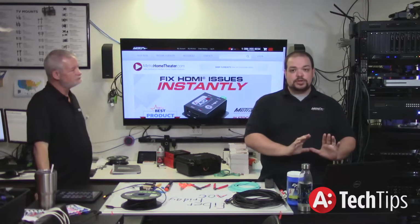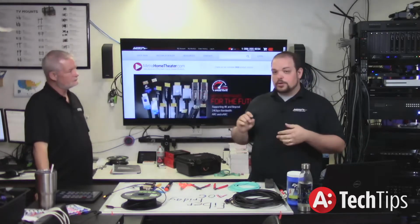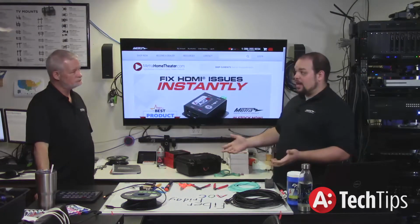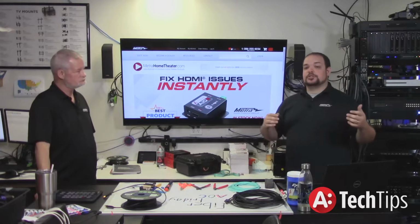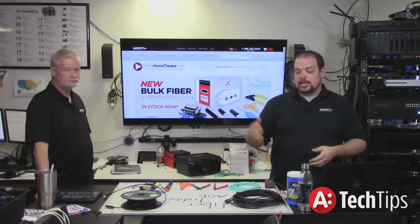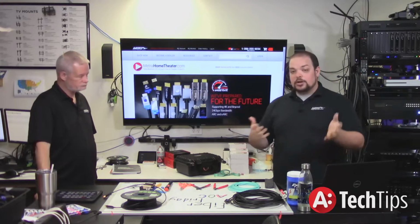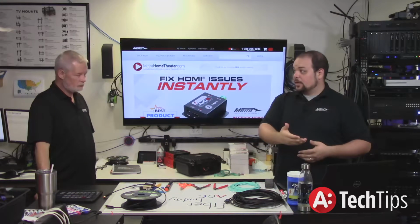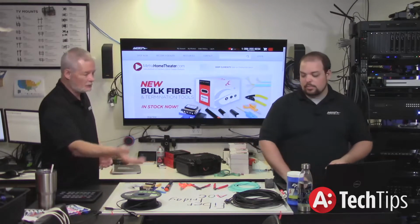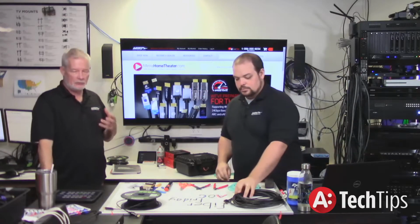If you're going to be using it solely for an HDMI connection, put in an HDMI AOC cable. If you're doing a pre-wire and you have an opportunity to put the bulk fiber in, and in the future you're not sure exactly what you're going to use it for, whether it be data, video, or whatever, you put in the bulk fiber, because then it's there as an available channel to get whatever you need at that location. The nice thing with an AOC is that any of them from us, the install bay, regular or detachable head shell, you've got easily 4 to 6 years of legitimate usable lifespan.